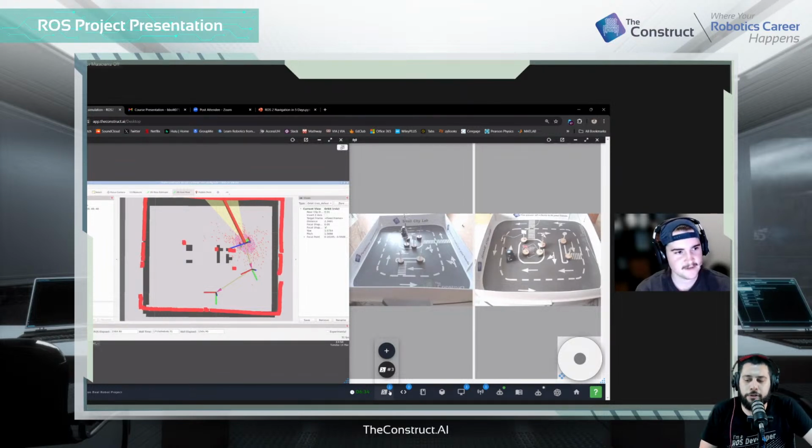So for navigation, right now you're running your navigation nodes on the construct, which is wherever you are in the world, and then the robot is in another place in the world. It's actually running the TF, the odom, the scan that is needed, and that communication sometimes fails. So if you do it all together, that's why it always works either in the sim or the real robot, if you select base footprint.